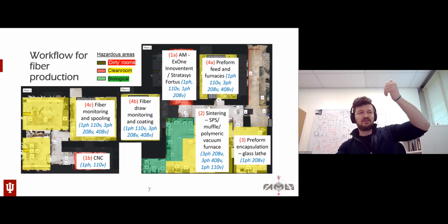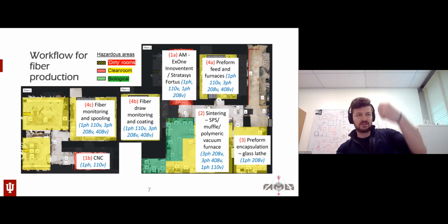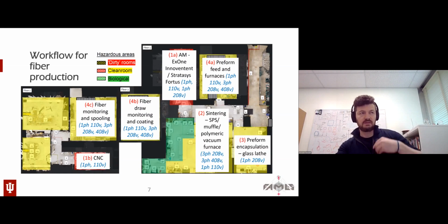Then the fiber drops down, carrying with it a thin strand, which is the beginning of the fiber. On the lower level, a tractor grabs on it. So you have automated mechanics to start drawing the fiber. Then that fiber goes through coating. That coating is cured by UV lamp. After that, the fiber is monitored for the thickness and spooled on the lowermost level.